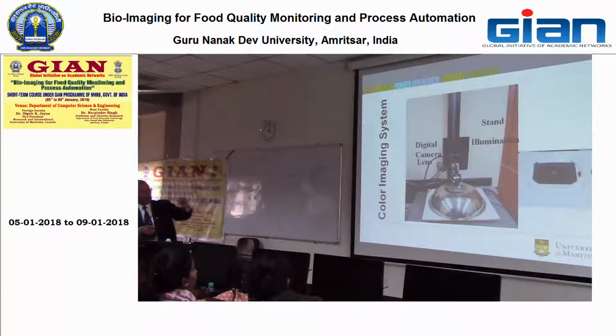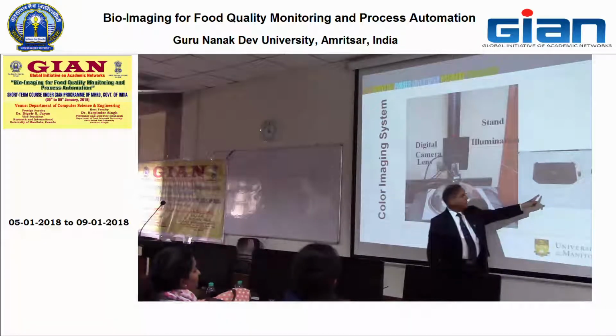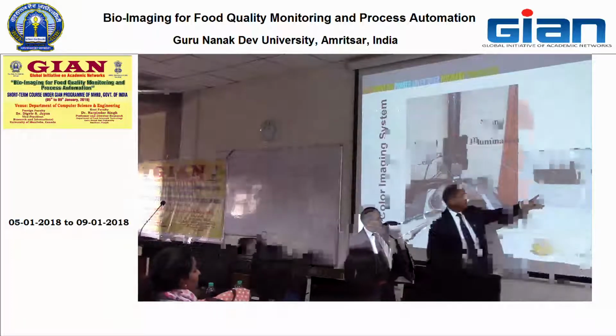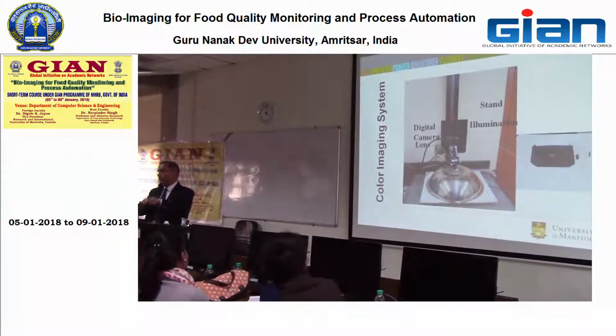In this particular example, there is a circular fluorescent tube around the area, which is not that easily visible, but that circular fluorescent tube is the one providing the light around the object. And this dome, which is an aluminum dome painted white with metal oxide on the inside, reflects the light from the fluorescent tubes back. So it gives a uniform lighting on the surface where you are putting the objects and taking the images.